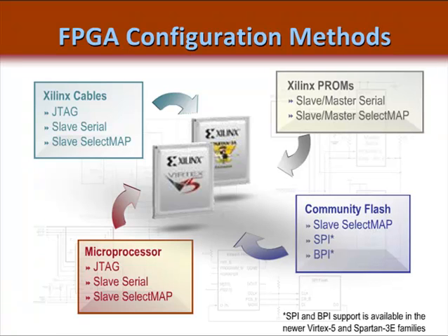Note that to this point we have discussed having only one configuration mode. In reality, most customers want to debug their prototype and then later program the FPGA with a different configuration scheme. To do this, most designers build some simple control logic which will allow the system to switch between the 2 or 3 configuration schemes of choice.